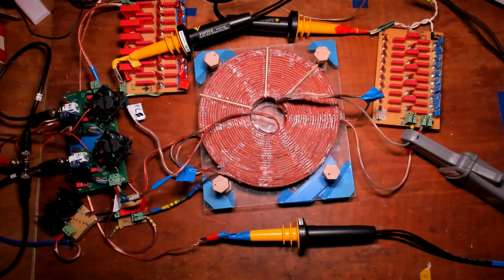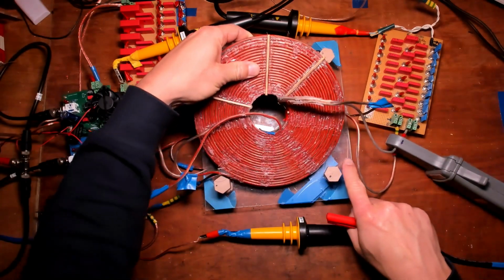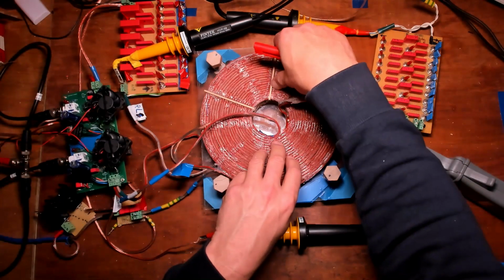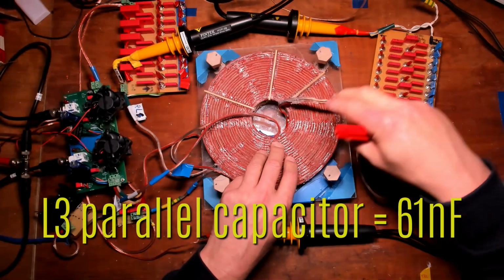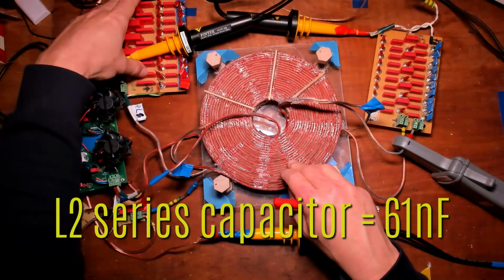Let me first explain the basic setup that you are seeing here. Here is the stack of pancake coils. There are 3 coils together here. The top 2 coils are close coupled together. The bottom one is distanced by this distance holder. The top coil is the L1 coil. The close coupled coil in the middle is L3. And L3 has a parallel tuning capacitor here. And the bottom coil, which is distanced, is the L2 series resonant coil, which has a series tuning capacitor.